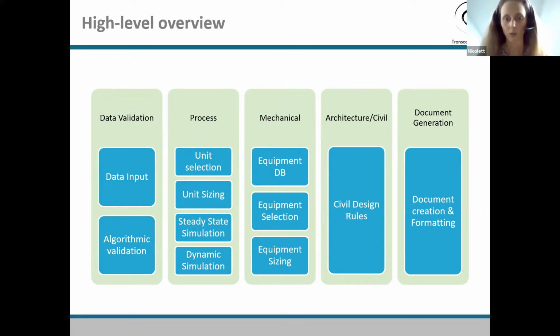If not, then we are adjusting something within the facility, like reactor volumes, DO set points, recirculations. So anything that you would do manually is done by the tool here. And when the steady state simulation has reached the point when it's saying that the limits are met, so this facility is going to work, then we are also running a 1-year-long dynamic simulation where we are taking into account the yearly variations in the temperature and of course the daily fluctuations of the influent wastewater.